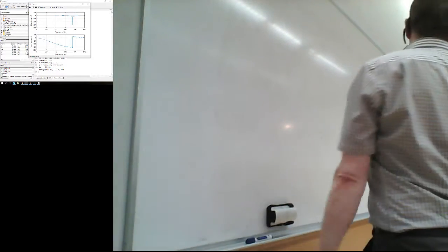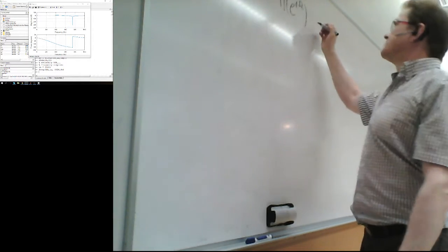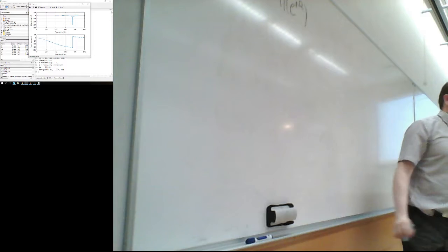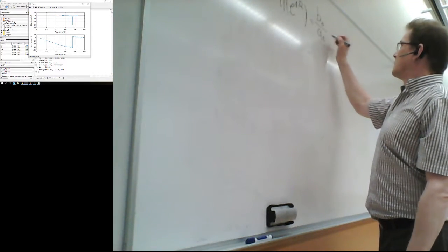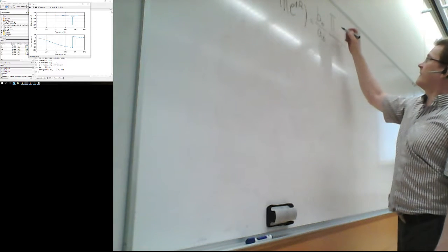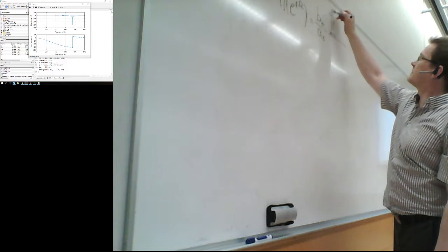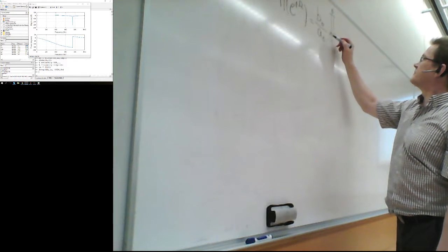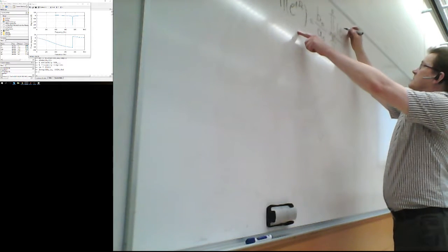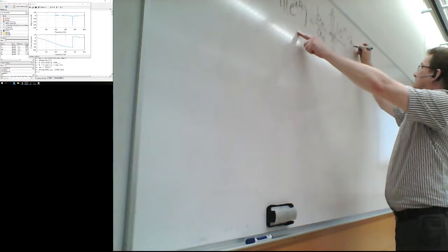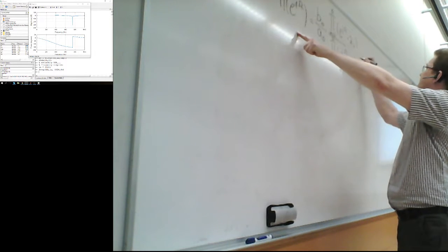All right, so my frequency response is also something like this. Remember yesterday, the product form of the transfer function: product of e to j omega minus zk, over product of e to j omega minus pk.